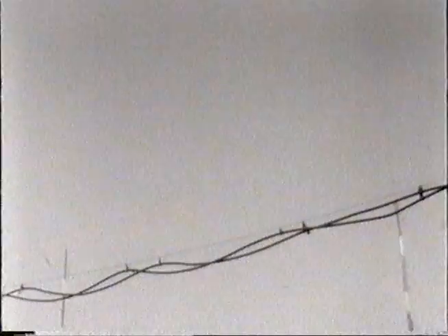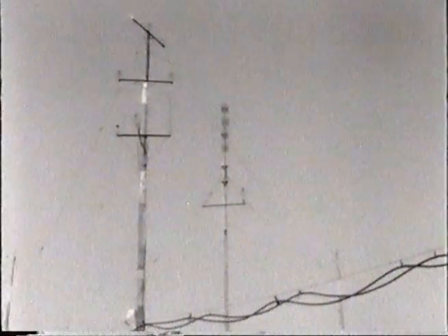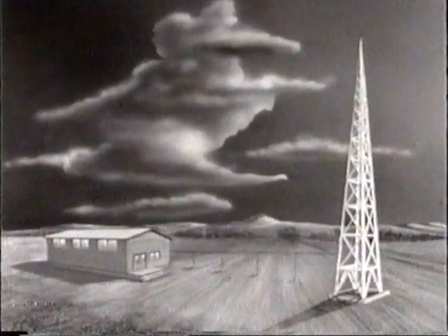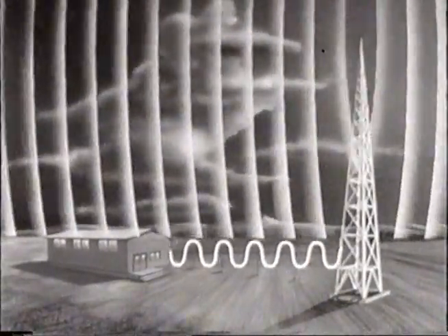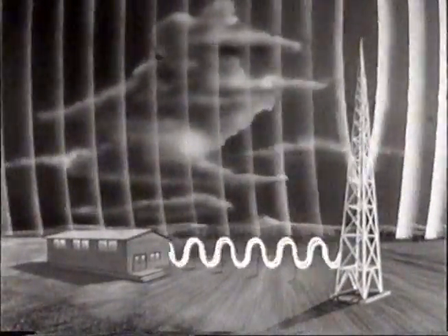But an antenna will not function alone. It is always part of a receiving or transmitting unit. Where the transmitter is at a distance from the antenna, a transmission line is necessary. The transmission line should carry only traveling waves. If any part of the energy is reflected back on the transmission line, standing waves result, and radiation falls off. Here we see both traveling waves and standing waves on the same transmission line. Every effort is made in the designing of an antenna and transmission system to prevent the development of standing waves.